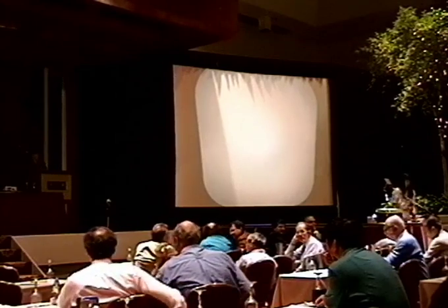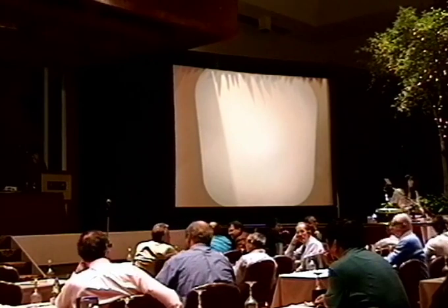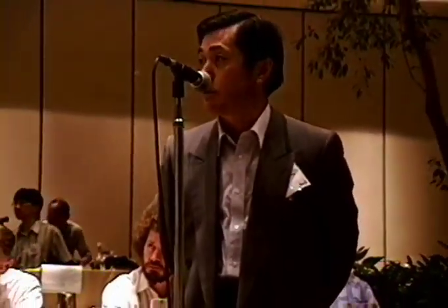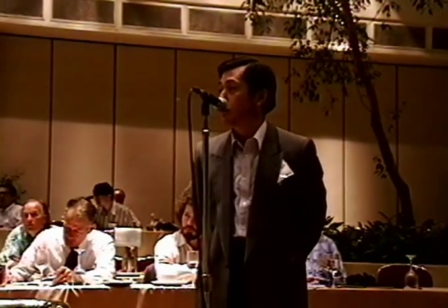Tom? A practical question: when you coat these electrodes with gold, do you coat the ends as well? And also, do you see any change or tendency of the gold film to peel off during the process? Yes, in our early experiment, we saw the peeling off, but we are now doing some additive treatment after we deposit the gold film.